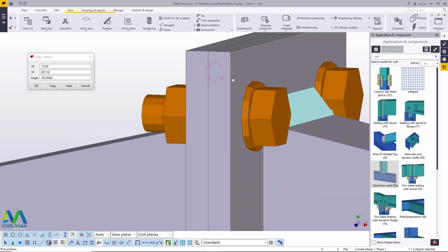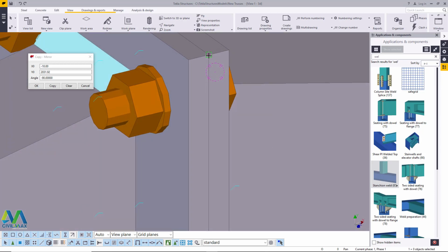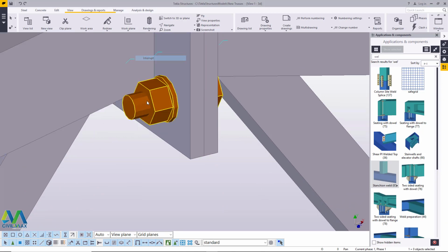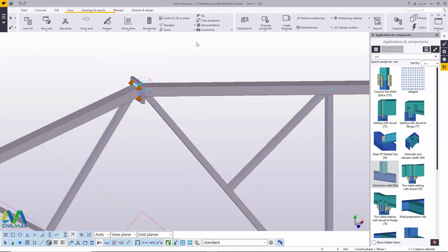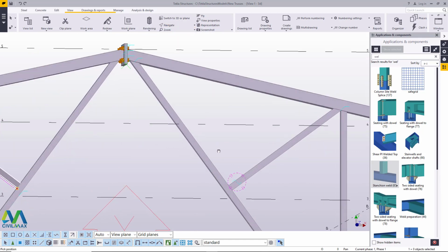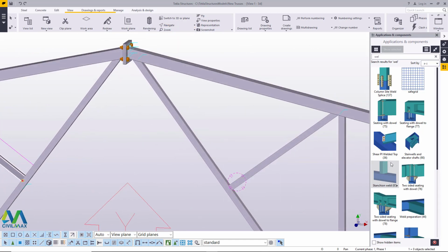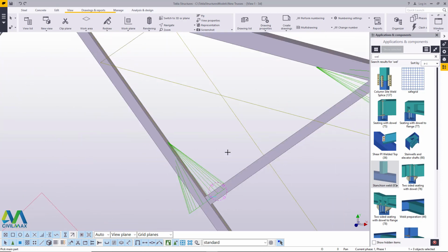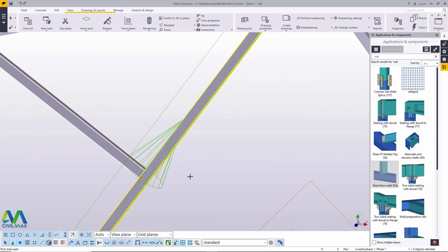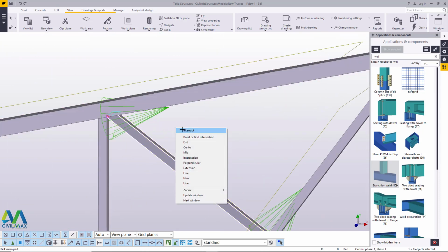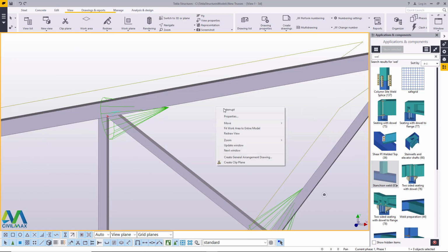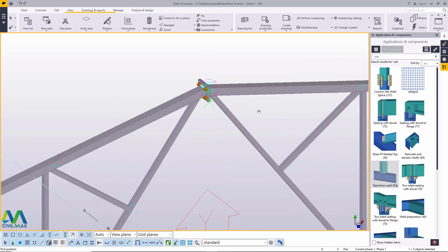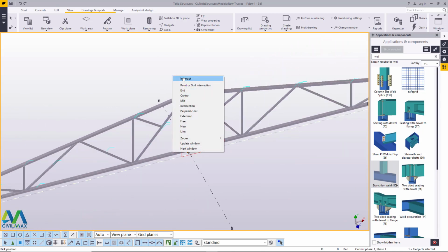Prior to snapping on your mirror points, make sure you are in the right position, and in this place, this is the position that I intend to use. And we have our member on that end. This is where we are. Now I'll come to weld, and I want to weld this member to that, this to that, that to that, and this one to that one. Perfect. And right click on empty screen and click redraw. That means you refresh everything to remove any signs of active macro in place.